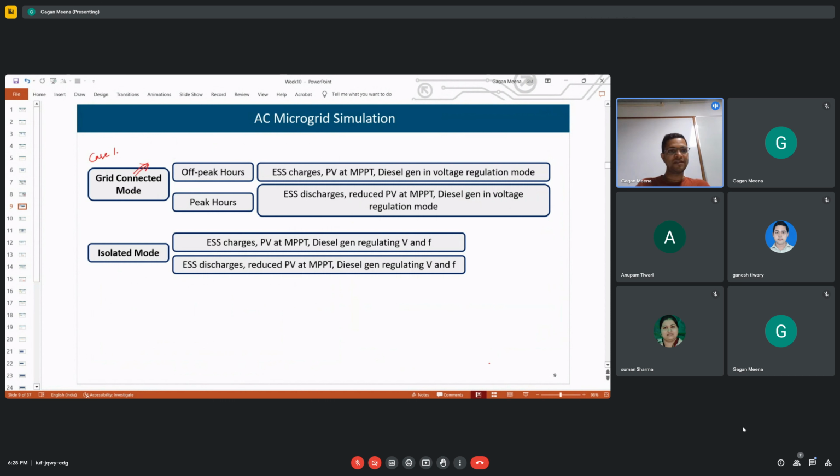Let's say slow is made master and then fast will follow it. And then third, it introduces the time delay in the operation. This delay is introduced for the fast one, for the operation of fast. So by introducing this delay, we can ensure both of them work simultaneously and share the reactive power requirement. Is this clear?